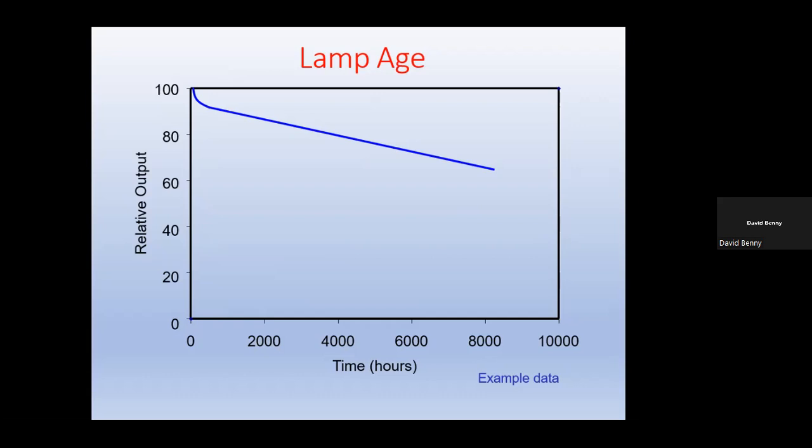So at the Beetham wastewater treatment plant, we have medium pressure lamps. It is advisable that these lamps will have a working life of 2 years or otherwise, based on the quality of water. So if you're sizing your system, generally small wastewater treatment systems will use low pressure lamps and large wastewater treatment plants will use medium pressure.